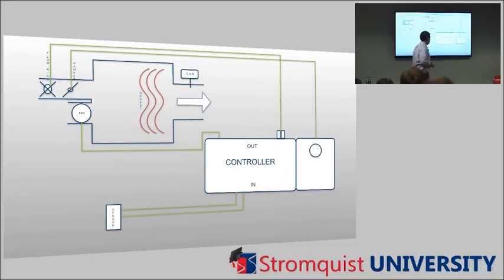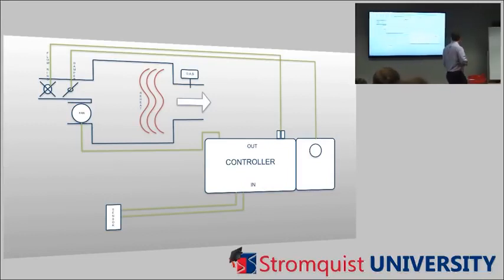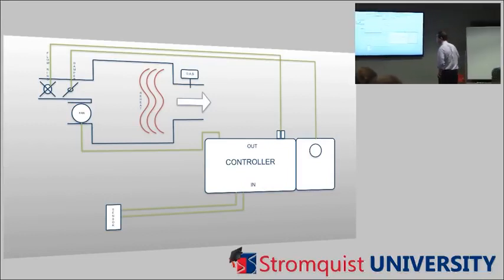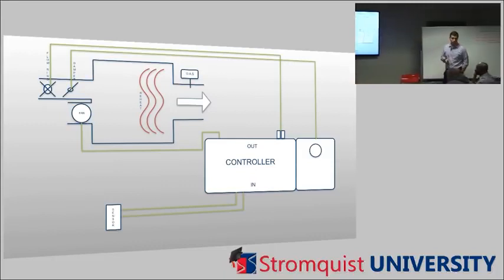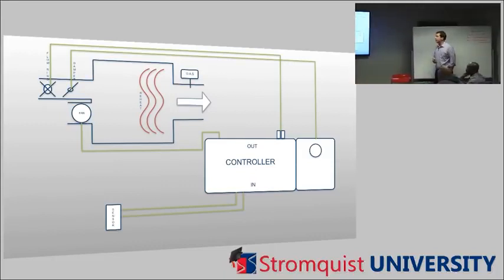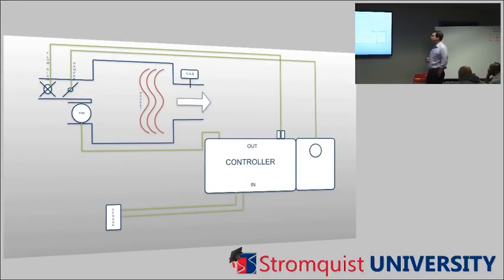What we got next? Reheat. So think about that again. They can answer too. See, it's all right. I thought he phoned a friend. All right, so reheat is the same thing, output, right? So the sensor's telling us what's in the building. We're outputting to the reheat mechanism to say we need to heat this air up, right?